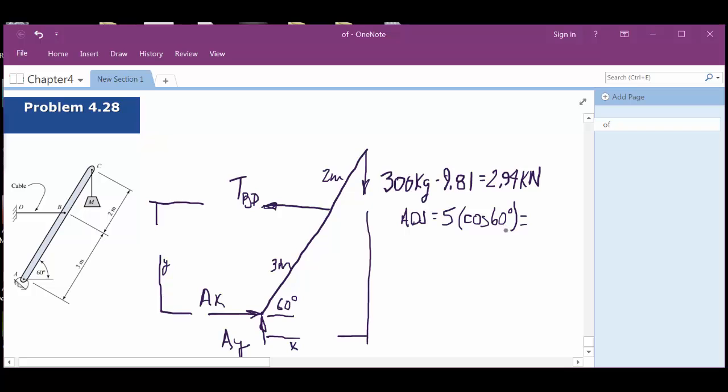I was going to ask you how come we don't need x2, or the distance where point B hits the beam? Right here? Yeah, you just don't need that because there's not going to be any moment equation calculated from that. We only need this x value for the one that's going in the y direction, and we only need the y value for the one that's going in the x direction for the moment equation. And the sum of the forces in the x and sum of the forces in the y don't use any values anyway, do they? So that is actually 2.5. Sorry, yeah, 2.5 meters. Thanks, Clark.